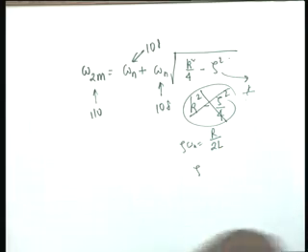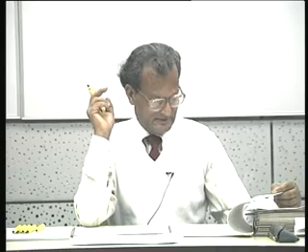Well, the other way is, if you remember, in a single tuned circuit at current resonance, that is when the current is maximum, the voltage across either the inductor or the capacitor is Q times the applied voltage. Did you know this? No, sir. Okay, it doesn't matter if you didn't know it, but now, at least now you should know it, and it's very simple to prove.